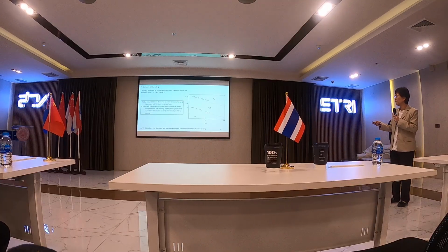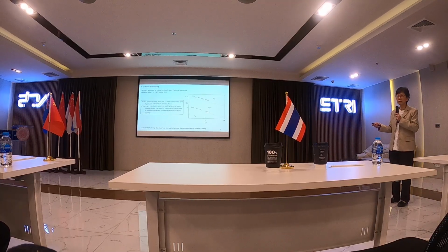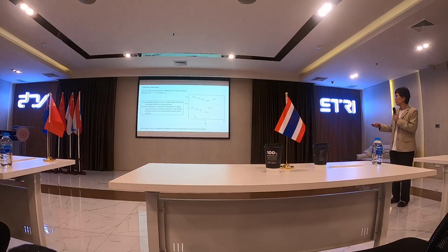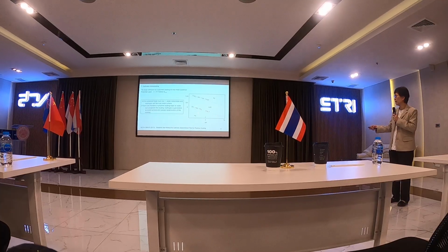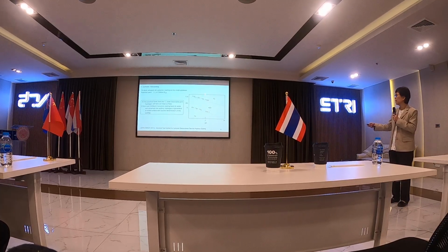Another test is cathodic disbonding. We use this to study the coating. In this Pourbaix diagram, you can see that in this range the water is stable. But when the potential is below this line, hydrogen will be formed, and above this, oxygen will be formed. So we will polarize the coating material until below this line, so the hydrogen will be formed at the surface.